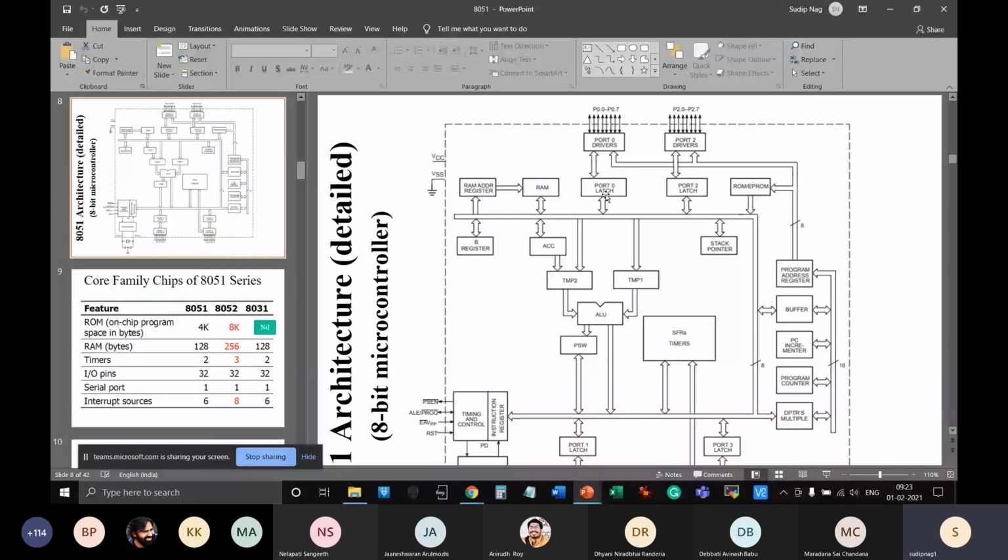So I'll repeat for MOVX A, @R0. Just very quickly, I hope it is quite clear now, but still. RAM has that R1 or R0 register. I want to copy that value and use that value as an address. That's why the value of R0 comes through these particular lines. It doesn't come to the accumulator, or go anywhere else.